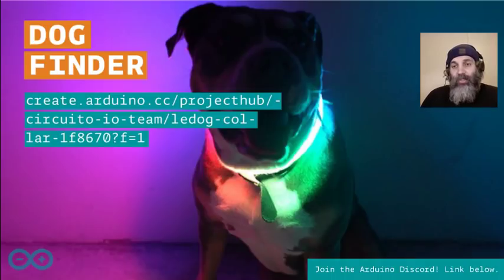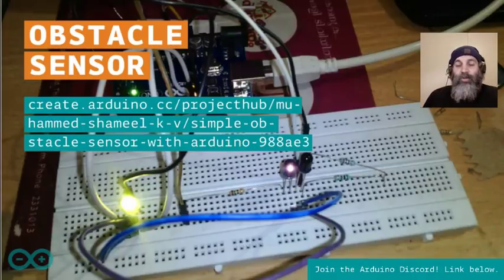And if you want to see another example using photodiodes and phototransistors, there's also this other project on Arduino Project Hub, which is the obstacle sensor. And the interesting thing on this one is that it's making its own obstacle sensor at a very low level using an infrared LED and a photodiode, or actually a phototransistor in this case. So the idea is that you can have a sensor that is detecting not just normal daylight, but it's detecting infrared light. And this is very convenient when you want to make a sensor that is typically used in a robot to measure distances or to detect a line painted on the floor.